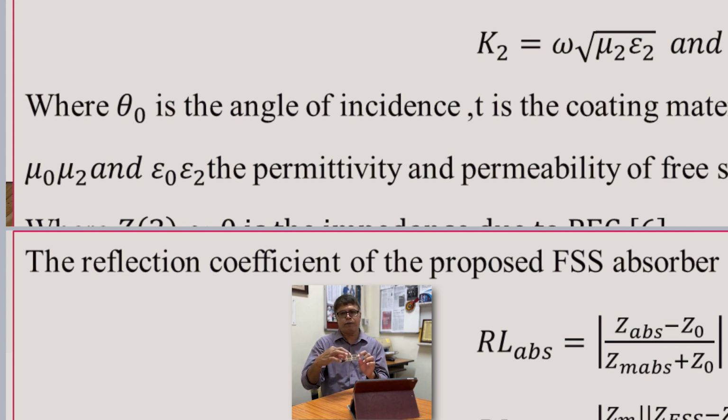So these three structures of ring resonators, or SRRs, or square ring resonators, or you can say rectangular ring resonators, are designed to operate at 2.4 gigahertz. These are the bottom layers, and if we see the top layers, these are square or rectangular ring resonators. They have a larger size compared to the bottom ring resonators. It means larger size will correspond to low frequency and smaller size will correspond to higher frequency. So for 2.4 gigahertz, these three ring resonators are there, and for the larger size, 1.6 gigahertz, these three ring resonators are there. They are coupled with capacitive coupling. Similarly, these three are coupled with capacitive coupling.